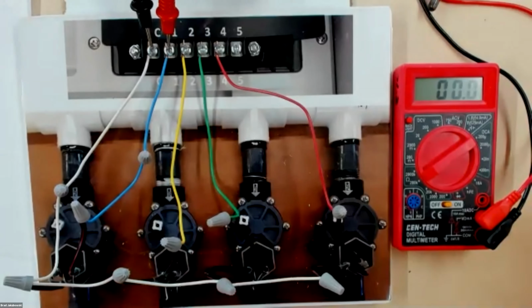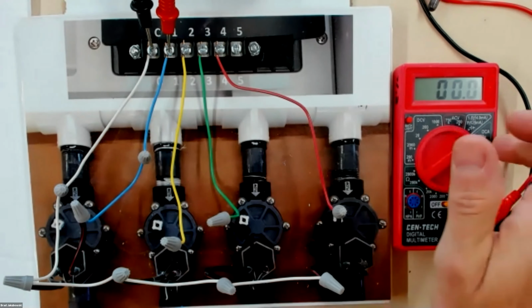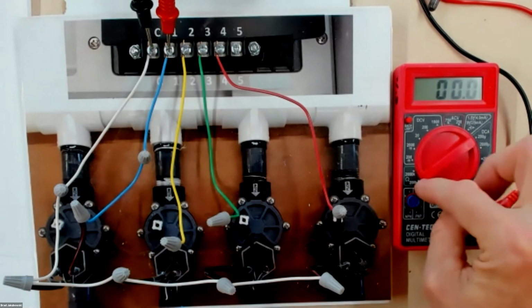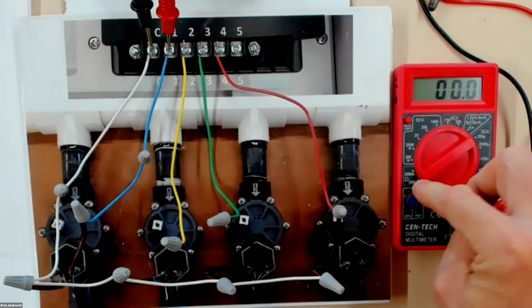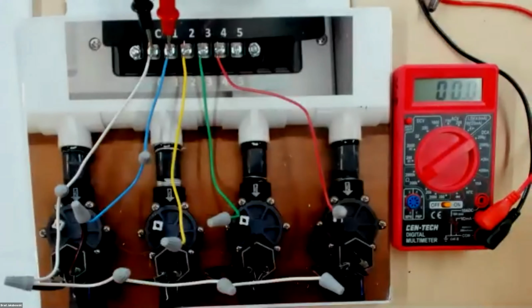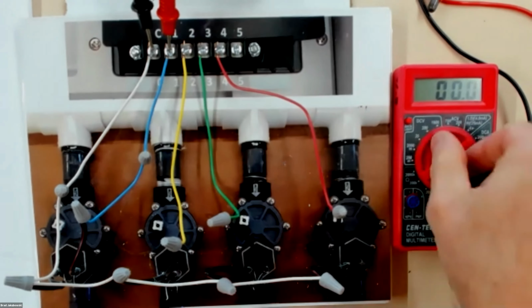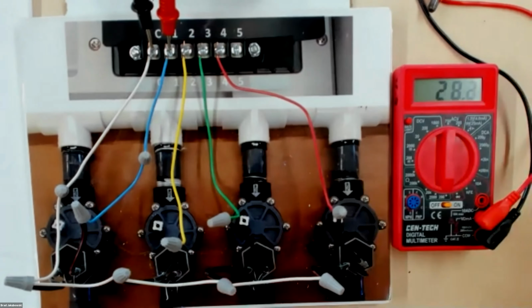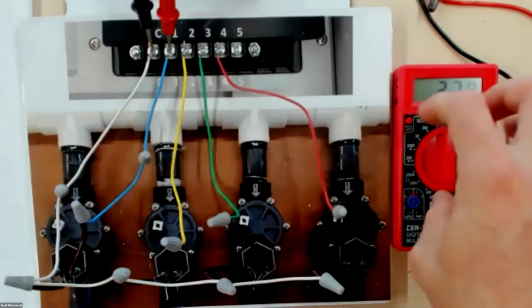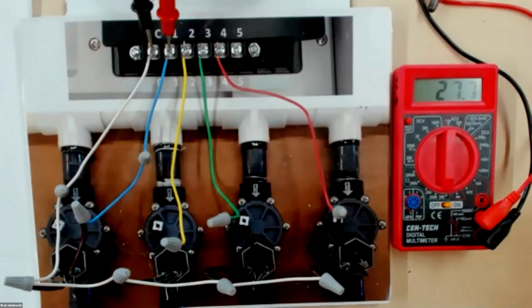And so that would be something, if you're doing a quiz or something like that, and you're handing these things out, have these multimeters set up at 200,000 and say, okay, test these and tell me, is it an open, a short, or is it operating properly? If they forgot to move this back down over to here, they're going to get an erroneous reading. That would be one way to test their knowledge of the use of a multimeter, and a little bit of critical thinking skills as well.